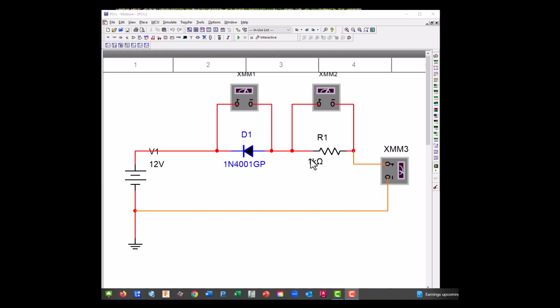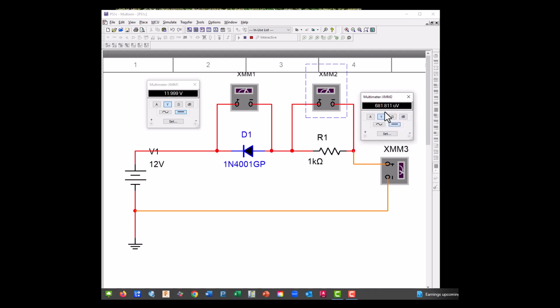And we're not going to have any current because we don't have direct flow. But it will give us the full value because our meter is essentially passing the voltage around it. So let's go ahead and start it and see what we get. And we get the full voltage, and this guy should be pretty close to 0. That's microvolts, and our current should be nanoamps, which is essentially 0.